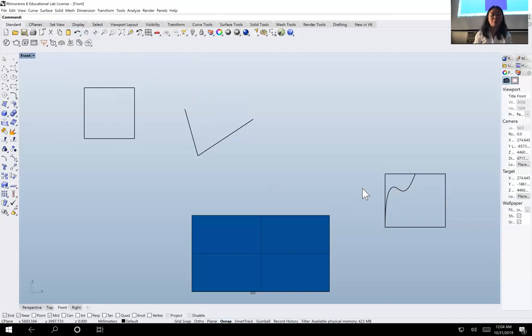Okay, let's do the mirror again. I have to type in mirror. Enter, select the object, press enter, select this point, good. I'm going to do the trick that I've been doing a lot, which is press shift, because shift makes it only go vertically, and I click. When you mirror, you have the axis for mirror. You cannot just mirror anywhere.